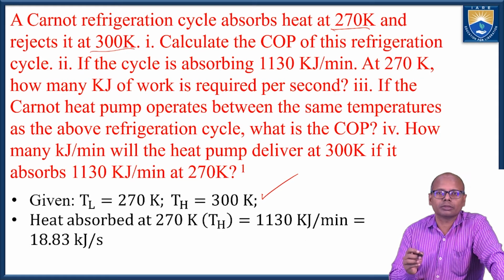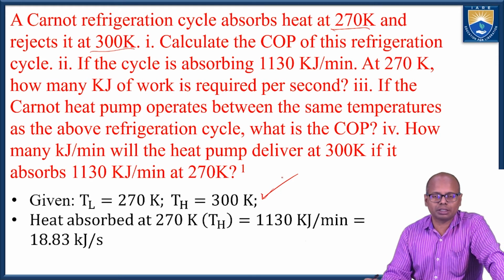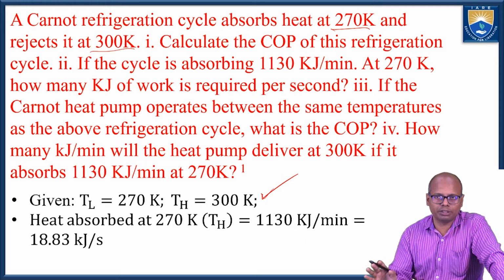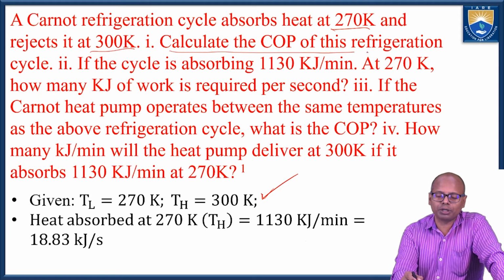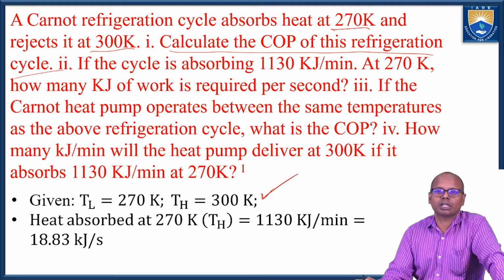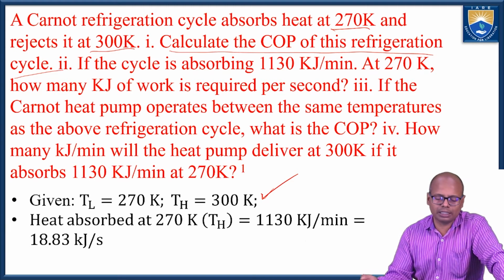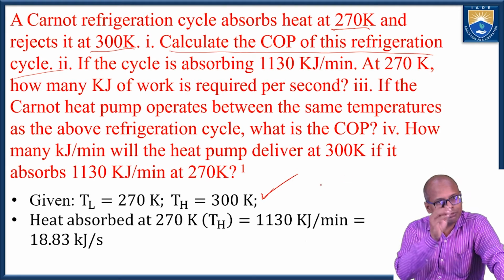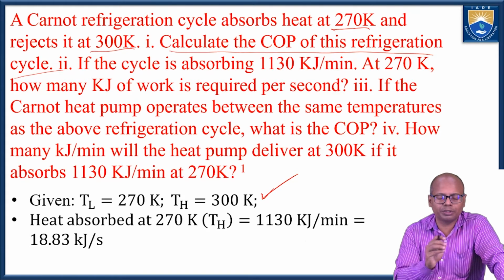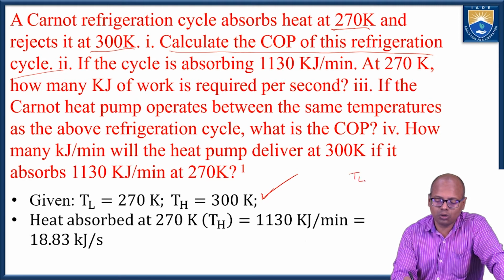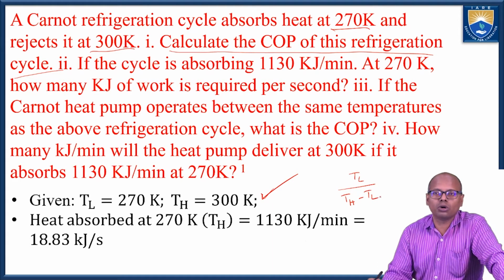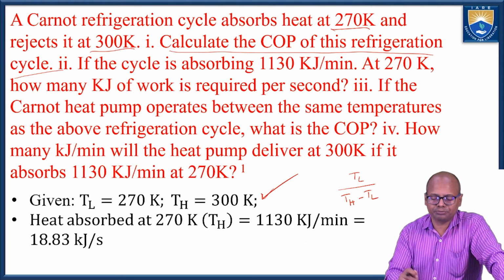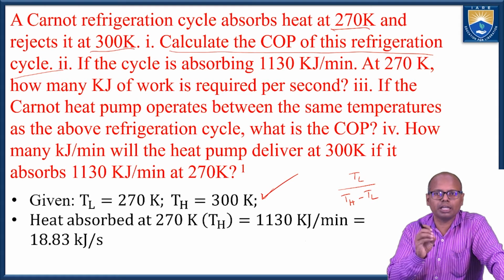What are the units of the temperature? The temperature must be in Kelvin for this kind of problem. Now, the first bit is to calculate the COP of this refrigeration cycle. So what is the COP of the refrigeration cycle? It is very simple. As soon as refrigeration comes, the numerator is the lower temperature divided by the higher temperature minus the lower temperature. This is the COP formula for a refrigerator.